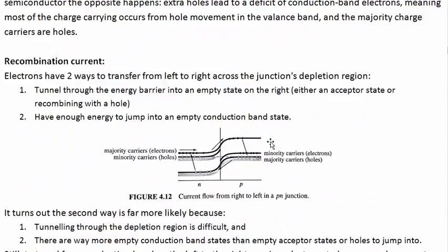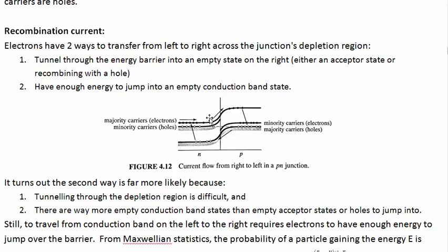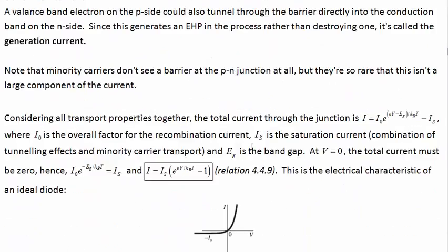Let's go back up to the band diagrams. In order to forward bias this diode, we need to raise the energy levels here relative to there. So to raise the electron potential energy, we need to put a negative charge here. That's going to raise this up relative to this side. If we put more positive charge over here, that's going to mean it's a lower potential energy. Electrons would gain kinetic energy by going over to there. So that means we need to put positive on the P side and negative on the N side. That's what forward biasing a diode would do.